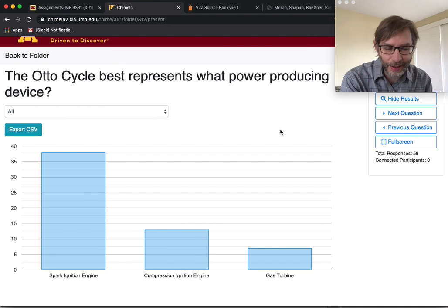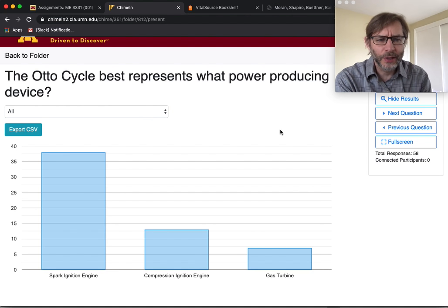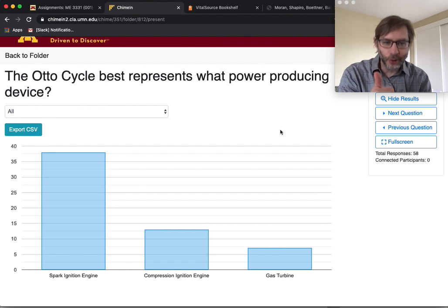You don't want that, and I really don't like it because I've said it so many times that I feel like I'm repeating myself. So just to reinforce that: for the Rankine cycle work that we did with the steam power plant, use the tables. Do not use the ideal gas law. For the stuff we're doing here, for the last lecture on the Otto cycle and for the Brayton cycle, use the ideal gas law.